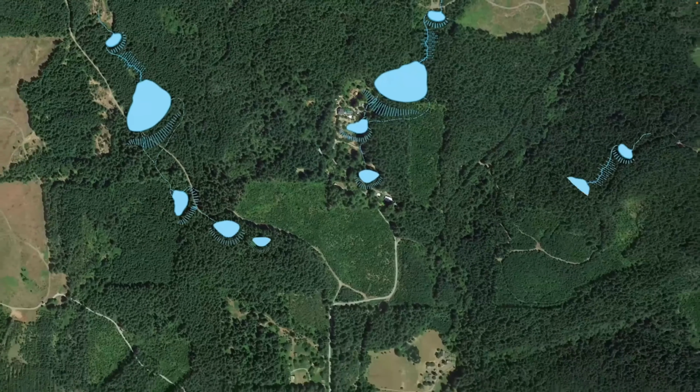So if we now look at the pond from a bird's eye view, we can talk about some other key elements. One is the spillway. The spillway is the way that we pass live flow around the dam. Every pond needs a spillway. The spillway needs to be designed to handle the flow or the discharge of the watershed through itself, and the ideal spillway is built to handle 3 times the total storm flow coming off of the pond.